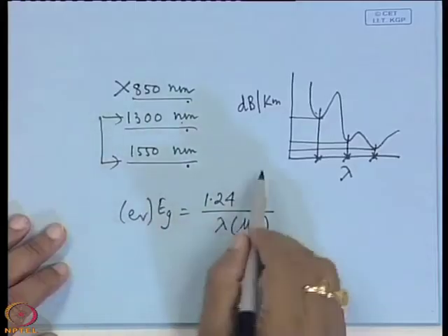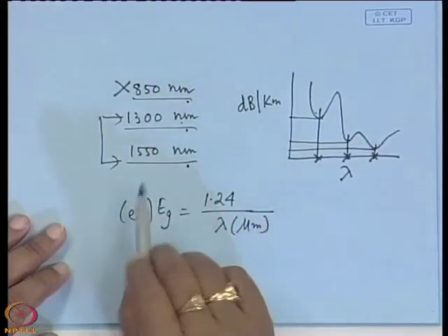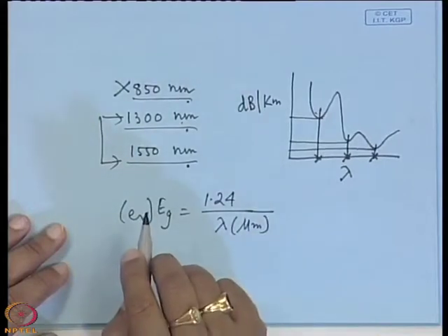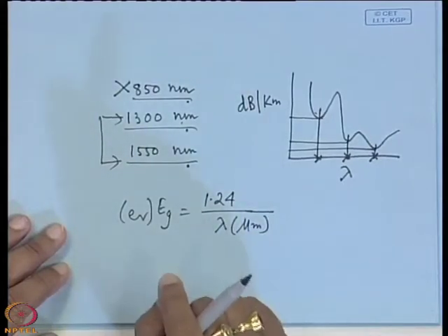Then there are some constraints also. One constraint is that these type of semiconductors are all epitaxial layers, because a device is made out of epitaxial layers only. A device cannot be made from bulk crystal. You will find that devices are always made of epitaxial crystals, that means some 1 micron, 2 micron, 3 micron single crystal layer.